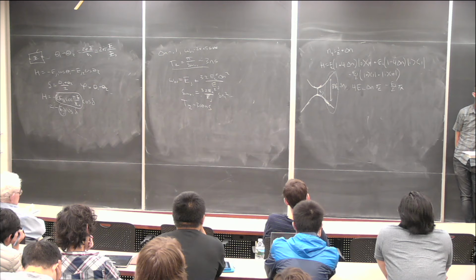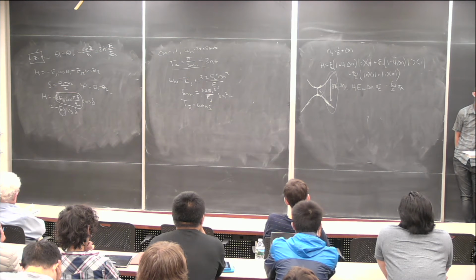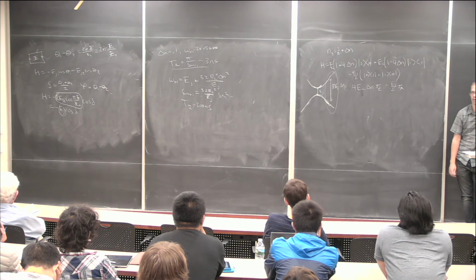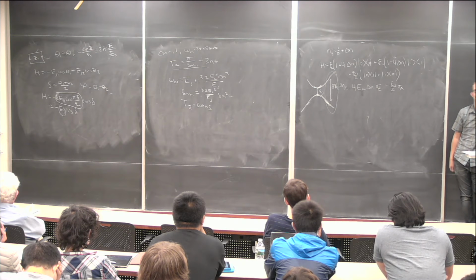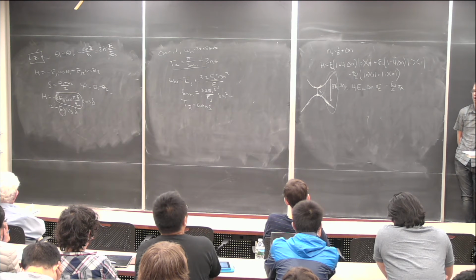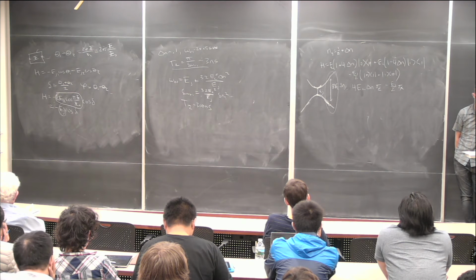And so a lot of folks are actually working with single junction devices again and getting rid of the flux loop and just working purely with untunable qubits, where the frequency of the qubits can't be tuned, and just hoping they're close enough to where they need that that you don't pay too much of a penalty for any lack of tuning, and then you can make them work okay.